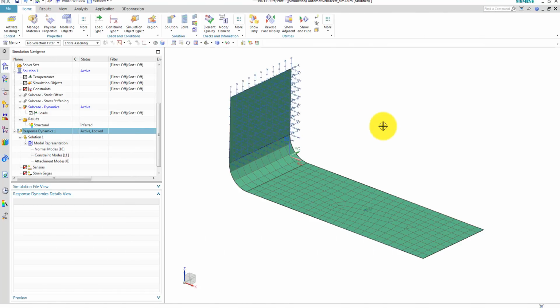Then I want to run a frequency response simulation. That means that the input excitations are a function of the frequencies. It's not a transient simulation anymore. The easiest one is probably a transmissibility study. Transmissibility is a type of FRF, frequency response function, that lets you evaluate the response of one or several output nodes to an enforced motion, such as displacements, velocity, or accelerations at a selected node. A common application is to study how wheel excitations and engine vibrations are transferred to the vehicle body.